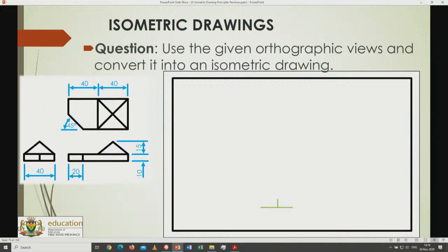Alright, so there we go with the final figure. In this case over here, again we start with point S on the bottom. There's maybe point S, B, or Q, or whatever the case might be, should be there. There's a few things I want to point out to you. If it's 45 degrees and you've got a dimension, remember 45 degrees with a dimension will also be the same dimension length towards the other side. If that is 30 degrees, it's not going to be the same dimension at both sides. But 45 will tell you. So if this is 20, I can make the conclusion that this will be 20, and that distance will also be 20 in the process.